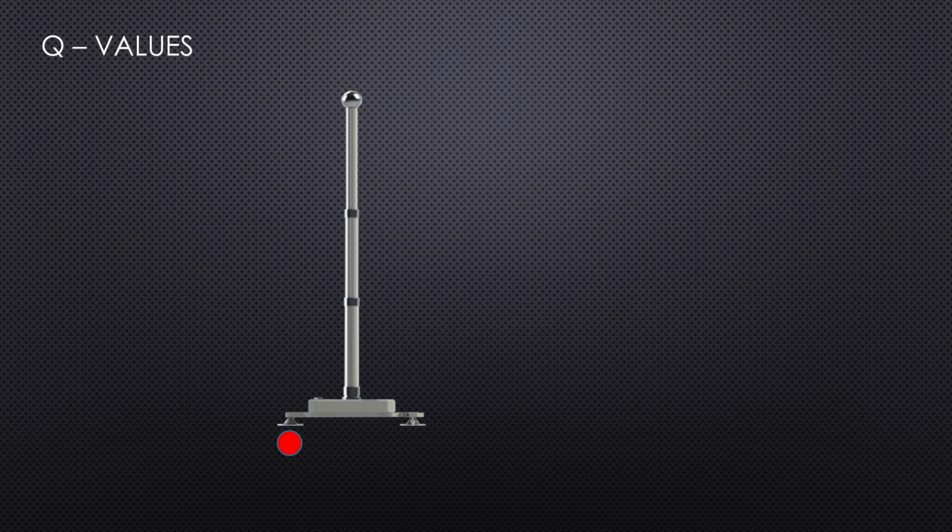Before I show you the rest of this animation, here is something we briefly touched on in a previous slide regarding the difference in a Type 2 device. Remember the subtle difference between a Type 1 and a Type 2 device is that you need 12 subsequent readings for a Type 1 device, but 11 for a Type 2 device. That is because the back of the foot of the device represents the first actual point, and once you gather 11 points, you have technically gathered 12 points. Now let's get back to what I wanted to show you with this animation.